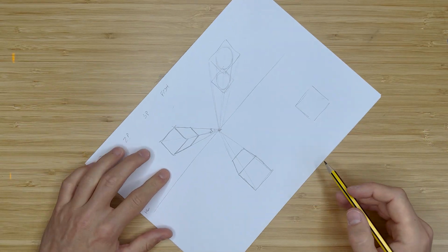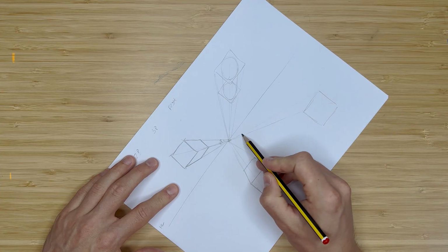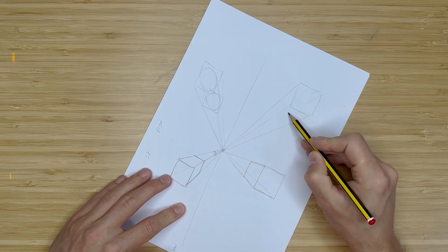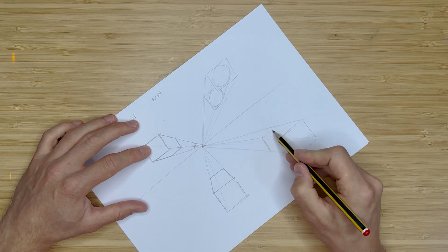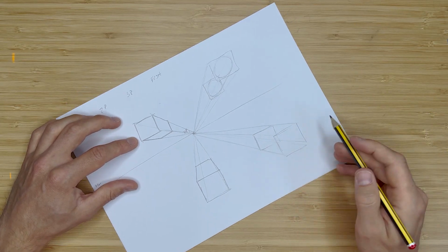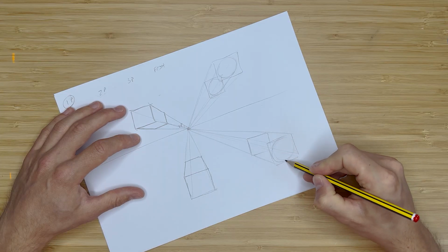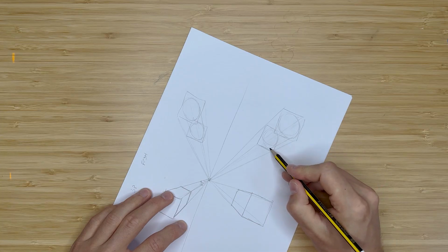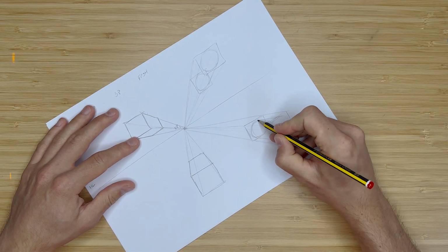Exactly the same down here. So hopefully you get the idea now. We're going to go from corner to vanishing point, corner to vanishing point, corner to vanishing point, and this corner to the vanishing point as well. From there, you're then going to find your verticals. So let's say we want this one here, horizontal, this one here. We can't see the back one, but we're going to draw it in just to help us with our construction. Add your cylinder on like so, or your ellipse, sorry. Another ellipse on the back here. Connect the two together. And then you're going to have a cylinder that is in perspective.